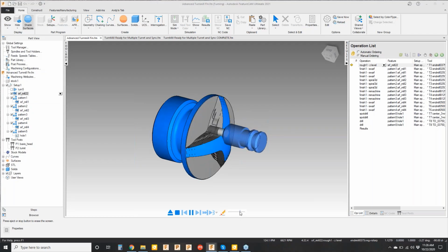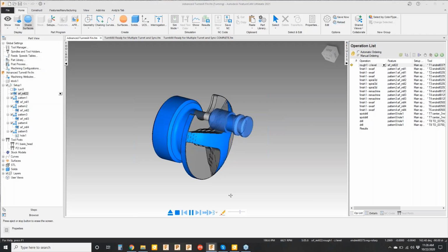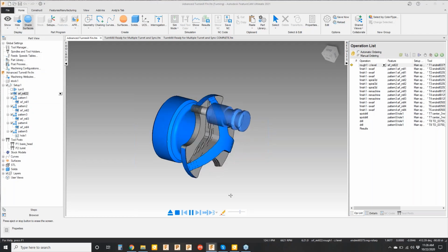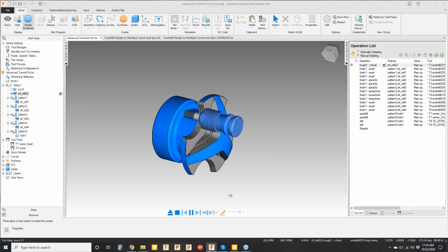Then there are some other toolpaths that follow this that are a lot more complex as far as what they do. You can see this is roughing out those 3 areas where we're getting ready to do the outer shape. And that outer shape actually has draft to it, so they're not parallel walls. That's why you see the steps that you see in this particular toolpath.